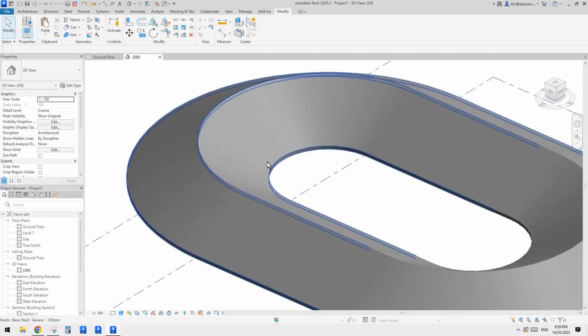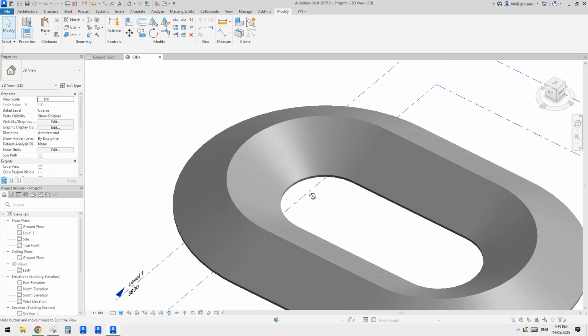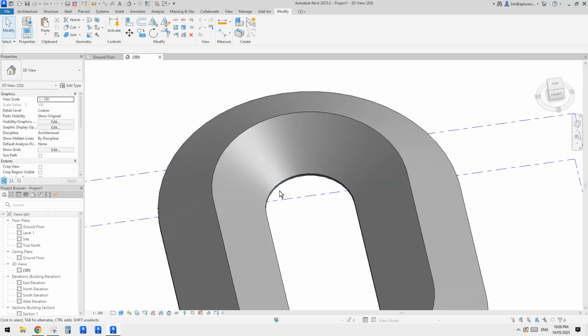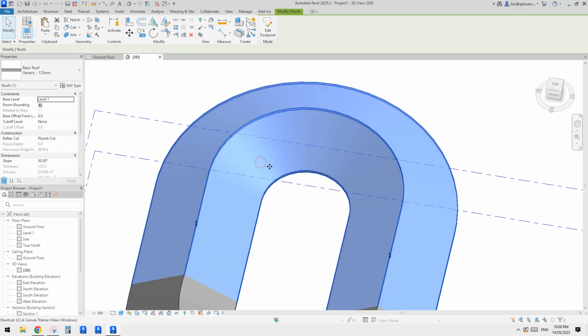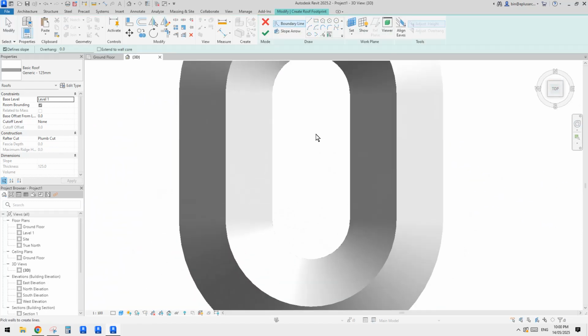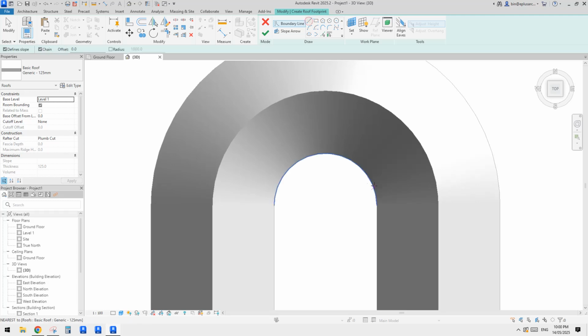So I guess what we can do from here is create a separate roof. Starting from here, this point and this point become a flat roof, and then slope, maybe just with a slope, right? And then back into this roof. So let's try. I'll just create another roof. Maybe I'll just click on top, so we can draw it on the floor plan, right?